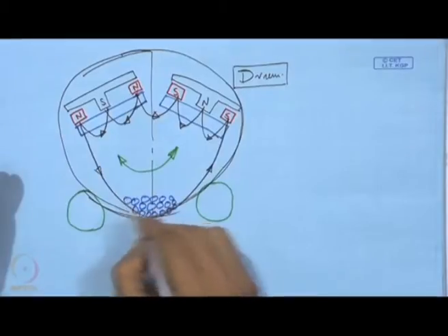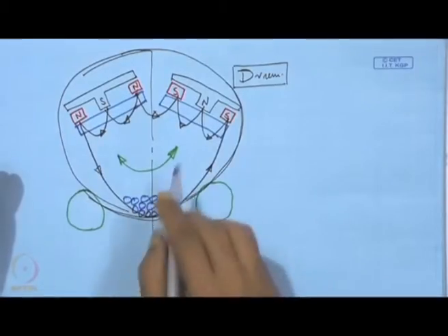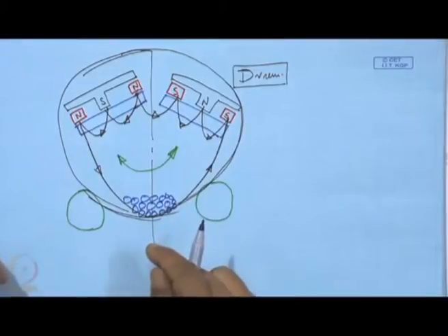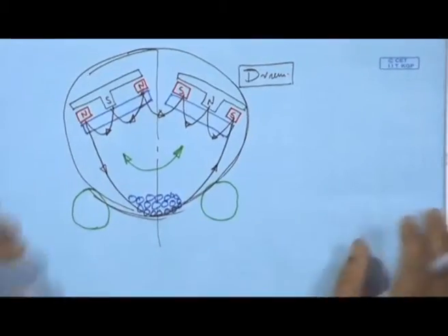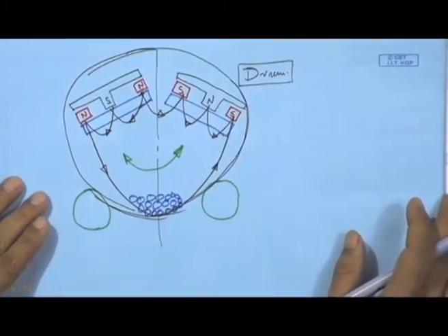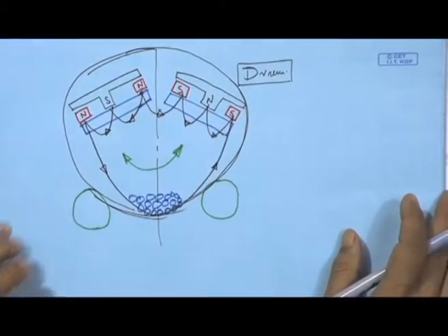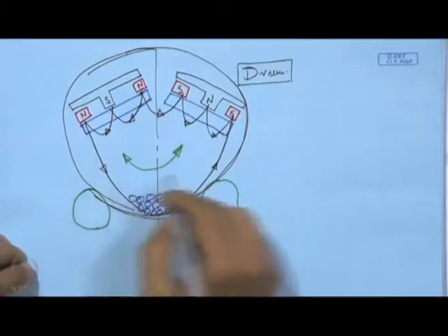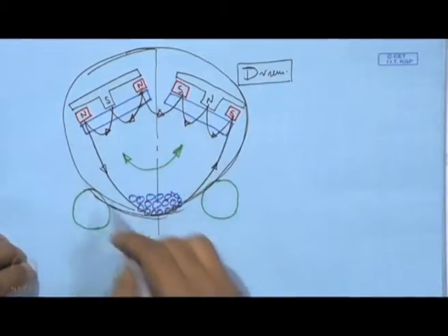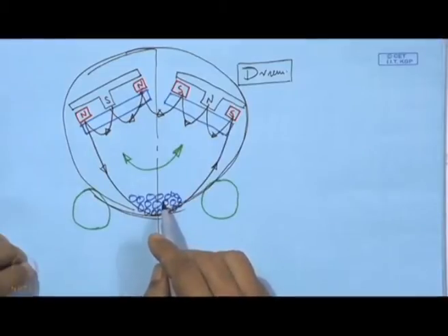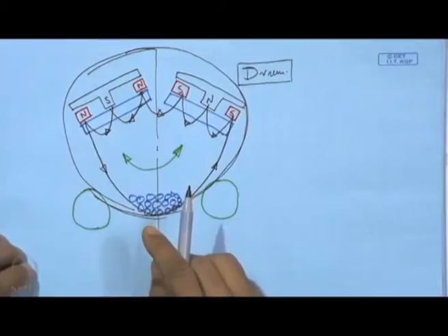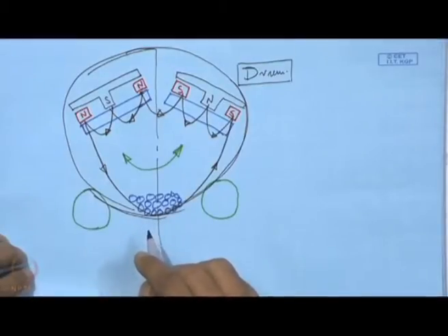And with that we can have a coating on grain-like things, on small parts, maybe the balls of a ball bearing or small mechanical components. By this tumbling motion and with this barrel coater we can also have this closed field unbalanced magnetron configuration, and with this we can coat these small parts.